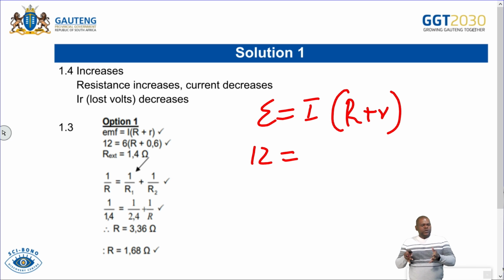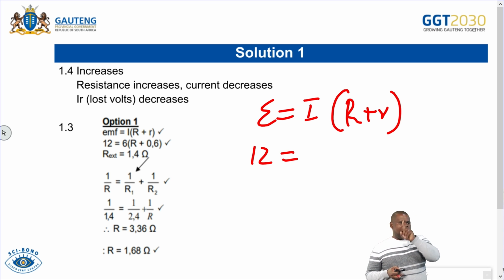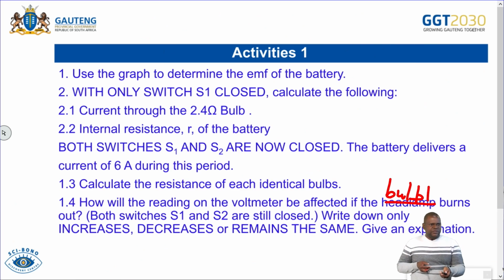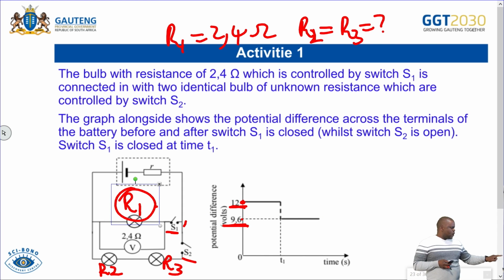Because we see that the connection is parallel, we're using this formula here. And remember, you can use another formula that says R total is equal to R1 multiplied by R2 divided by R1 plus R2. You can also use that formula, grade 11th. In this case, I just want to show you something. We're taking R1 and R2 as a component, we take them together as a group. Are we together?